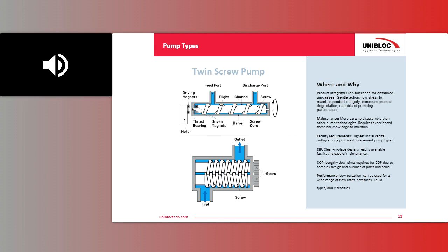So you can pump thin liquids and run the pump at higher speeds, and you can also pump viscous products and the pump runs at lower speeds or lower RPMs. So that's the big benefit. They can pump entrained air, and they have a wide speed range. So if you have a wide variety of products, from viscous to less viscous, this one pump can do all that.